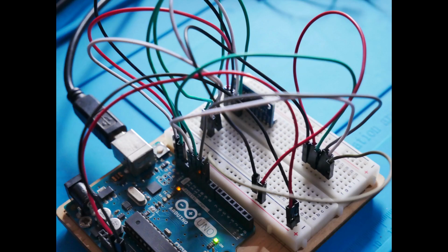One is UART, an abbreviation for Universal Asynchronous Receiver Transmitter. UART is a hardware module found in most microcontrollers, including Arduino boards. It handles the conversion of parallel data in multiple bits to send serial data in a single stream of bits and vice versa. For now, just know it's a transmission protocol for handling serial communication.